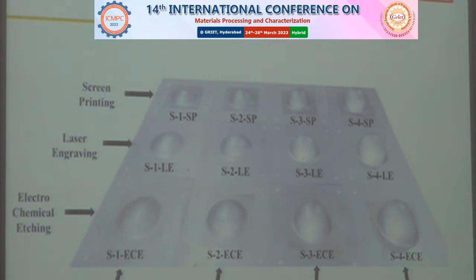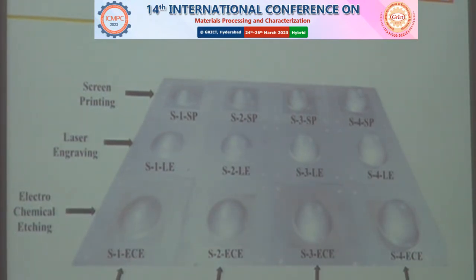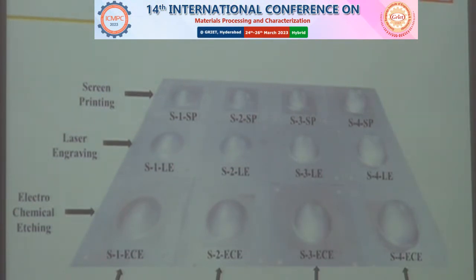I don't know how many of you know incremental forming. It is a die-less manufacturing process. Here we don't require any die, unlike deep drawing or stamping where we require a die. We will hold the sheet on a CNC milling machine, which many of you may know is used for cutting. Instead of using it for cutting, we remove the cutting tool and put one blunt tool with a hemispherical head. Then we generate the tool path. The tool path will guide the tool and it is going to deform the sheet in whatever shape you want.